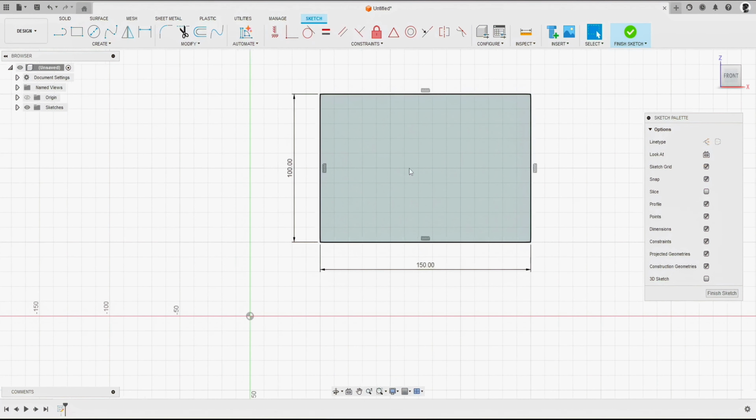And so it's a very straightforward tool to use. It's very quick, very effective. It's used often in sketching, although we can also apply fillets within 3-dimensional mode as well. So that's after we extrude a profile. We can apply fillets after that. Or if we're in sketch mode, we can apply them before. There is a slight difference between the two, and we're going to cover that when we move on to the 3D modeling section. So that's it for the fillets.